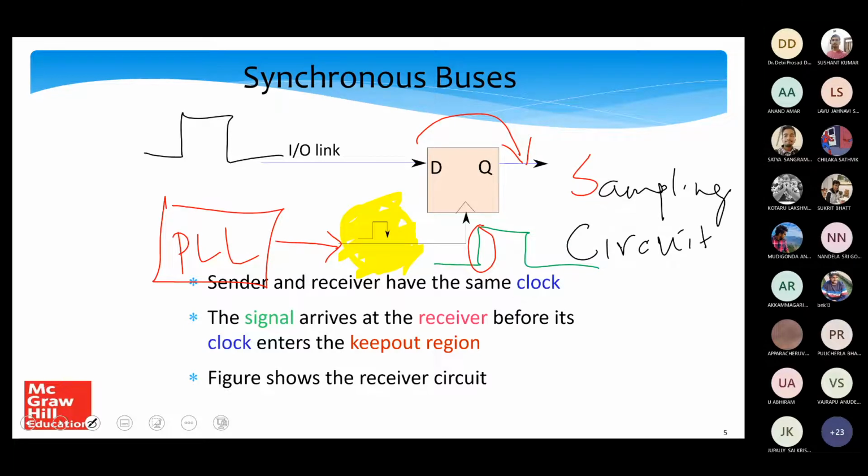Sampling circuit. Sometimes they call it a sample and hold circuit, because once you hit the bottom of the flip flop with that clock pulse, the D flip flop records what was there in D. So it samples at the positive edge and it holds until the next positive edge. So it's called a sample and hold. I hope you will be mentally filling out S for sample, H for hold. I'm not writing it there. But Professor Sarangi puts this diagram in his book, so you can all see that book. And of course, if you have Logisim, you can simulate this and see what happens.